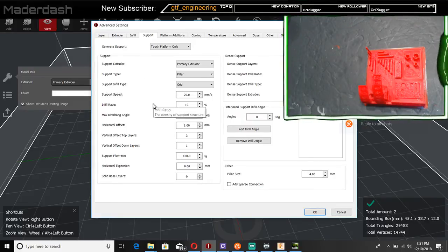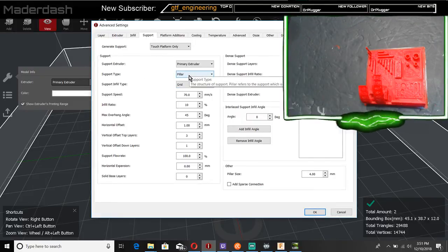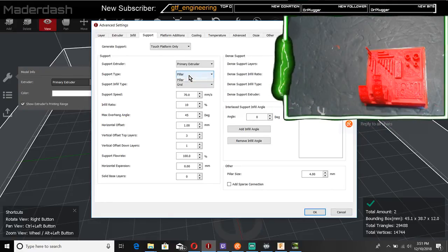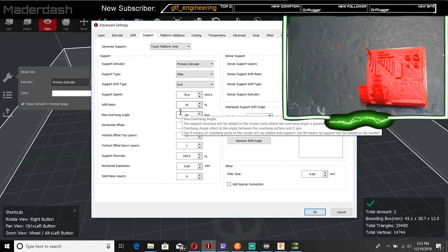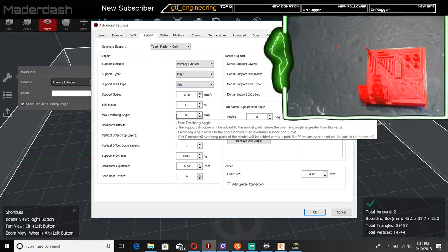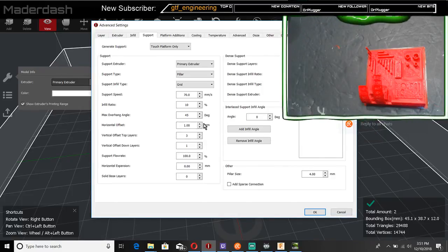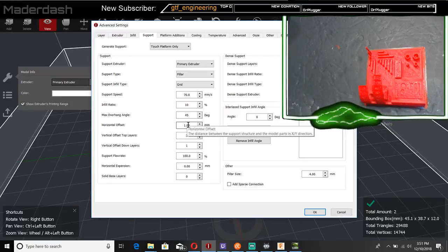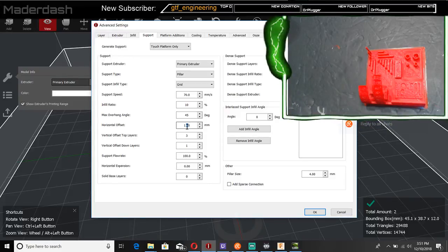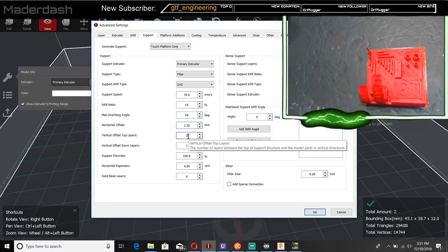And now we're on the support. Okay, I want it to be a pillar, a grid. Okay, horizontal offset. I want 1 millimeter. Let's make that 1.3. Vertical offset layers 3.